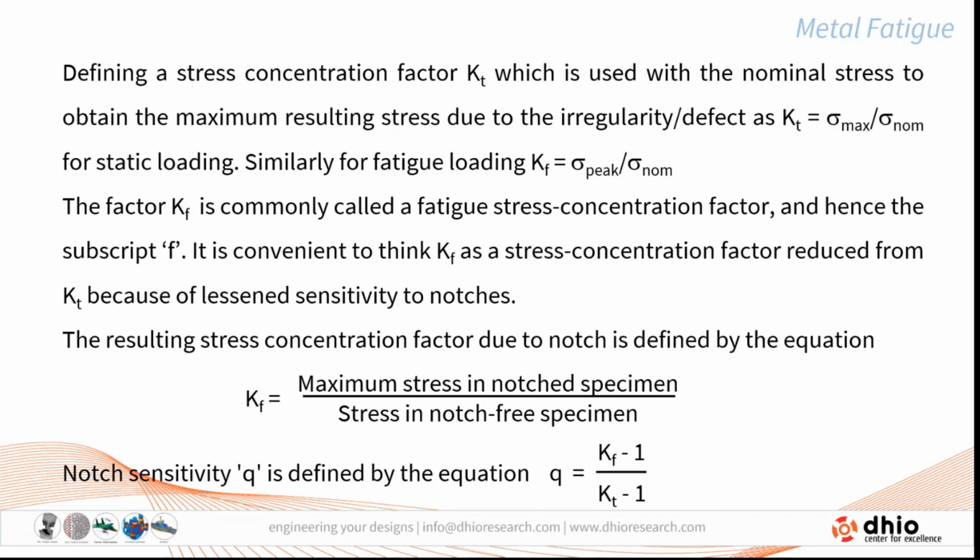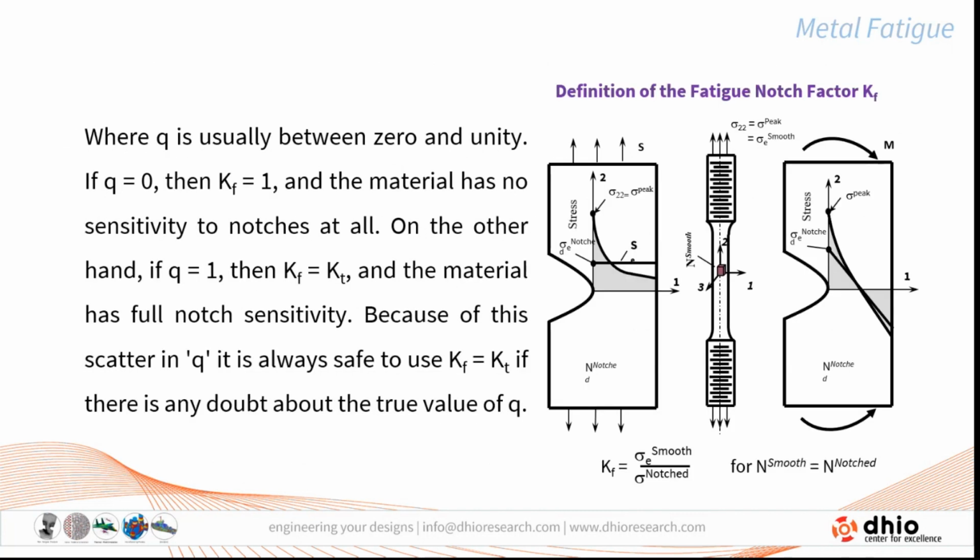Similarly, the fatigue notch factor, Kf, is defined as the peak stress to the nominal stress. With this, we have the notch sensitivity Q defined by Kf minus 1 divided by Kt minus 1, where the notch effect is taken into account.